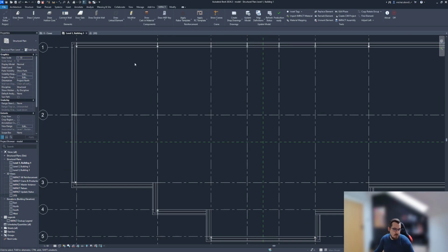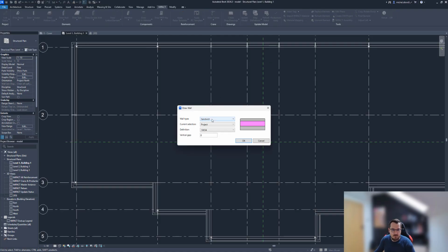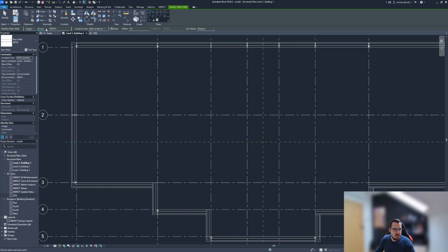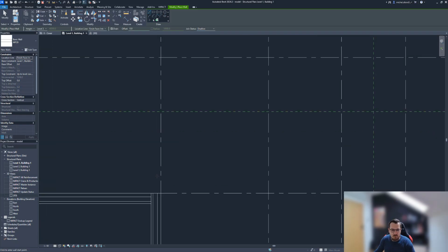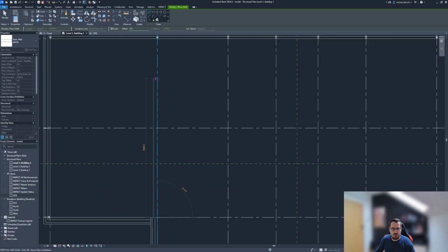And what we forgot to do, or I forgot to do, is I forgot to actually draw some solid walls, which I'll do right now for us. And let's actually start doing those. They're gonna be connected the same way. Wall, center line, finish, interior, disallow connection, and we're going to go like this to here. Yep.